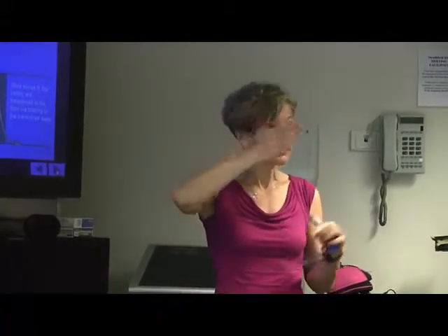What's the difference between structural and nominal bracing? Structural bracing is bracing panels, steel cross bracing, timber cross bracing, and nominal bracing is when you count the bracing that's created by wall linings, such as your internal wall linings. So the fact that your internal wall linings are attached to all your studs and produce that effect that it won't distort gives it some inherent bracing capacity, but it's nominal.